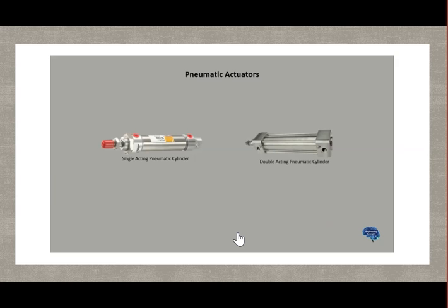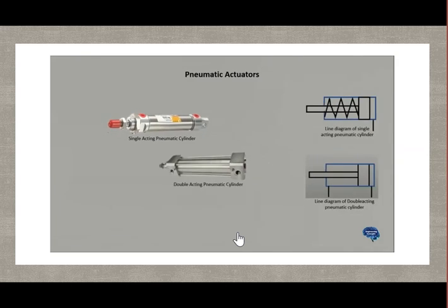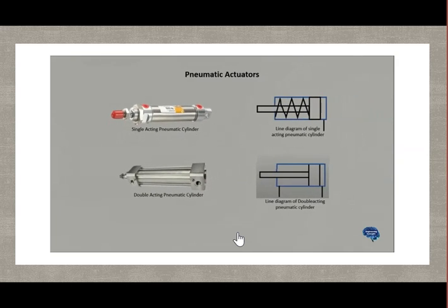Pneumatic energy is desirable for main engine controls because it can quickly respond in starting and stopping, as the power source does not need to be stored in reserve for operation. Moreover, pneumatic actuators are safer, cheaper, and often more reliable and powerful than other actuators. These forces are often used with valves to move diaphragms to affect the flow of air through the valve.